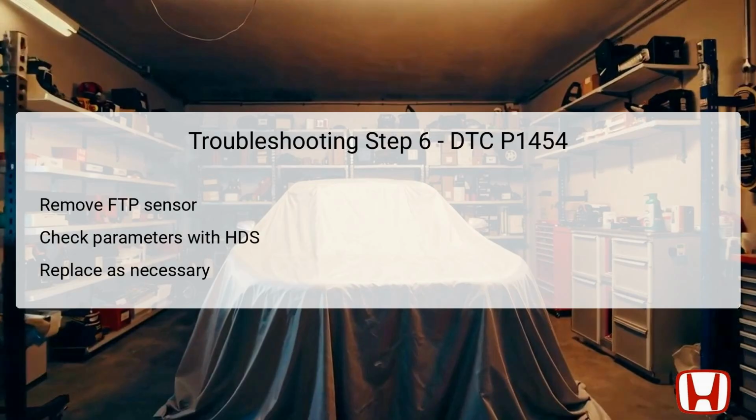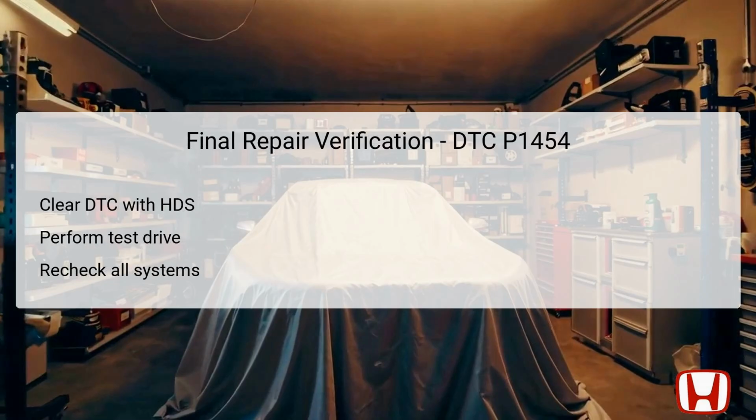However, if irregularities are observed, it would point to an internal failure of the FTP sensor, necessitating its replacement. Additionally, if internal blockages are suspected, the evap canister itself may require replacement, thus addressing the root cause of the DTC P1454.